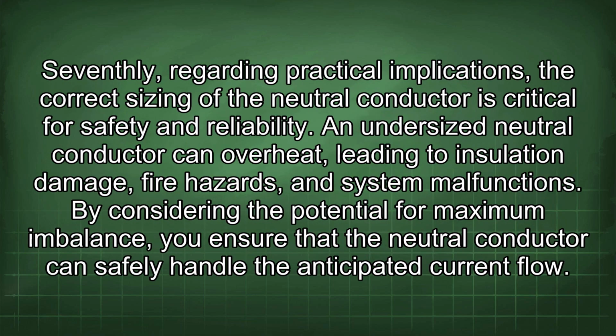Seventhly, regarding practical implications, the correct sizing of the neutral conductor is critical for safety and reliability. An undersized neutral conductor can overheat, leading to insulation damage, fire hazards, and system malfunctions. By considering the potential for maximum imbalance, you ensure that the neutral conductor can safely handle the anticipated current flow.